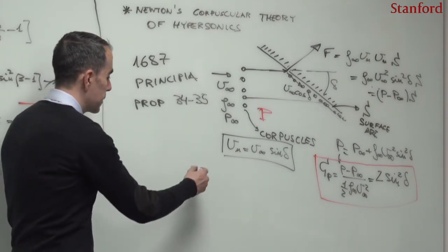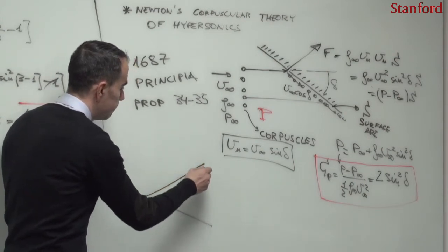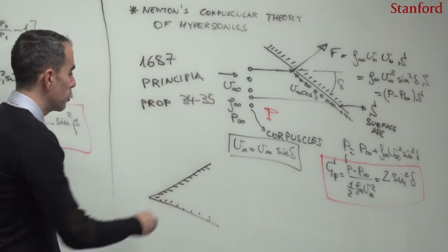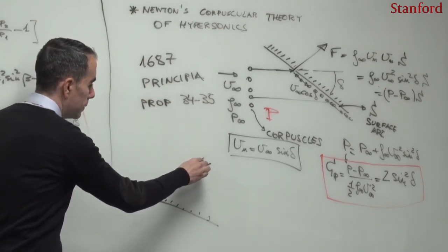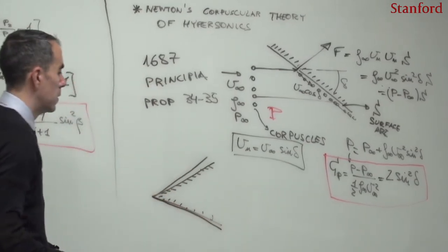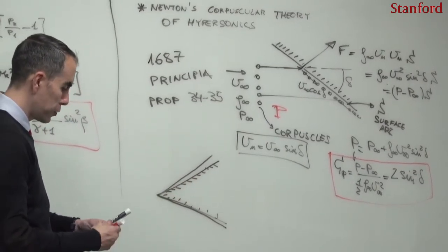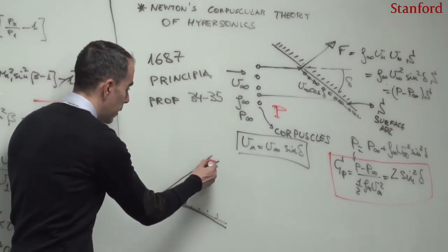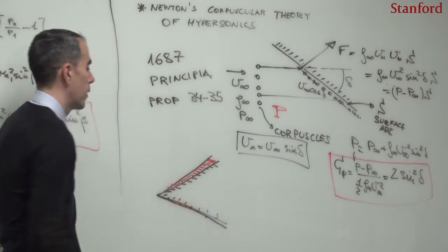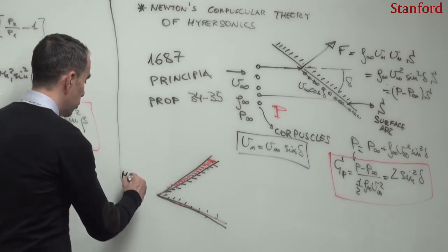If one takes, for instance, the wedge here, one is going to have a shock wave. As we discussed last time, this shock wave is going to be very close to the surface of the body. So there is going to be a very thin gap called the shock layer, where the gas is hot. Here the Mach number again is going to be large.